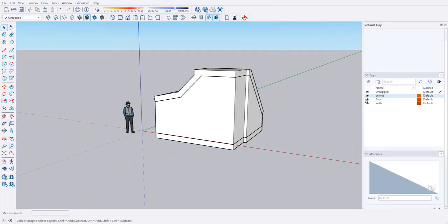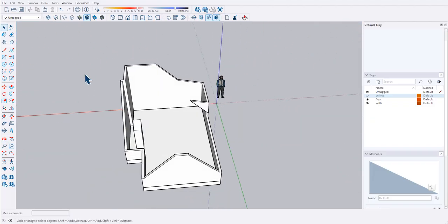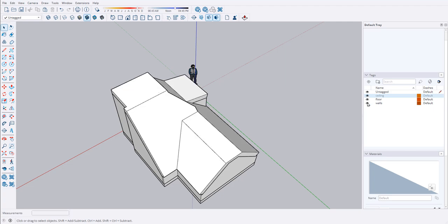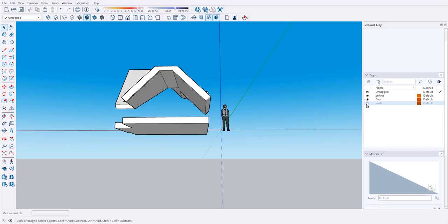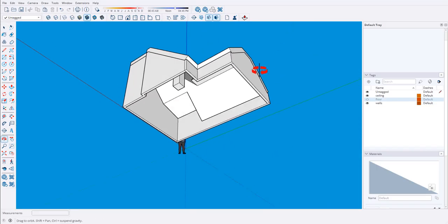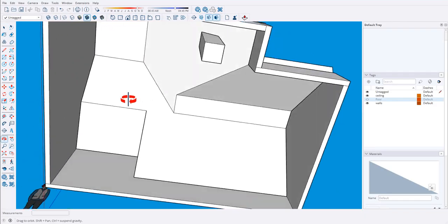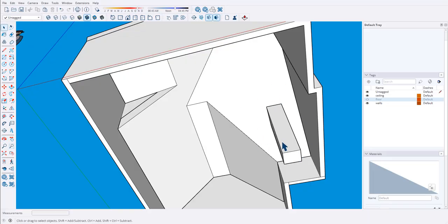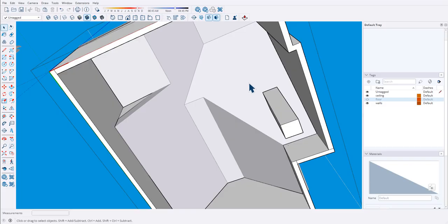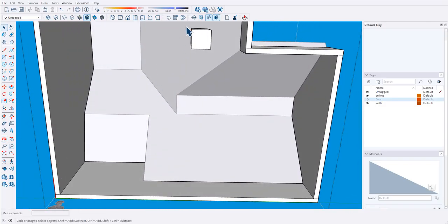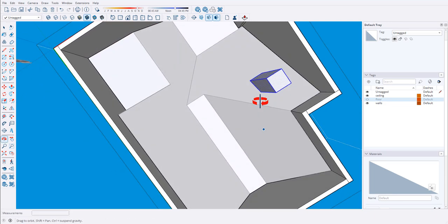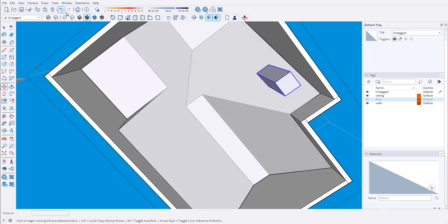All right, so this is what I have for your walls. And this is what your ceiling looks like as far as I'm concerned for your modeling. And if this column's not in the right spot, you can move it. I mean, it's in the wall component. If you hold it like this, and then M for move, you can move it over just a little bit if that's what is going on. I have a feeling that's really what's happening, but I'm going to move it back. You're going to put it in the right spot. So that's how you would do it.